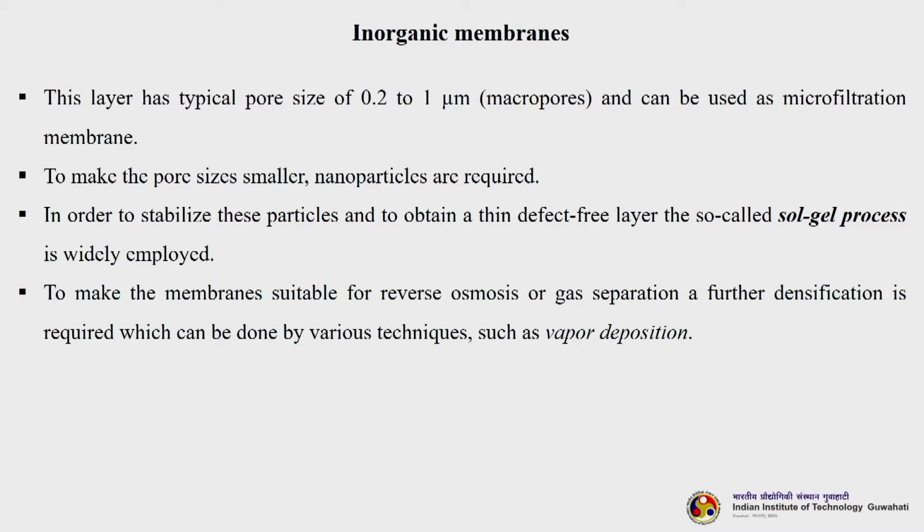This layer has a typical pore size of 0.2 to 1 micron and can be used as a microfiltration membrane. To make the pore sizes smaller, nanoparticles are required. So, in order to stabilize these particles and to obtain a thin defect free layer, the so called sol gel process is widely employed.